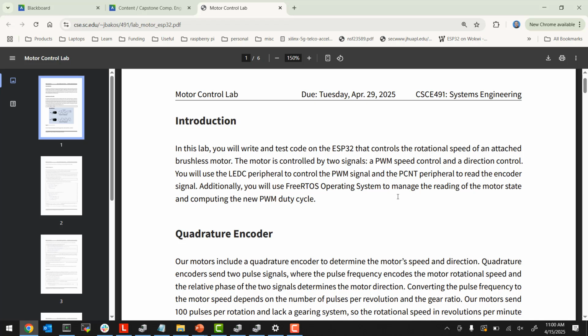However, I read online recently that even if you don't interpret the phases of the pulses as the direction, you can still take advantage of it. Because if you XOR both the encoder signals, it multiplies the frequency by 4, so you get 4 times the resolution. Instead of 100 pulses per rotation, you get 400 if you XOR the 2 signals. But we don't need to do that either. Don't worry about that, but keep it in mind.